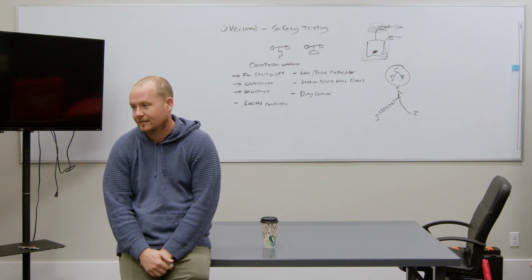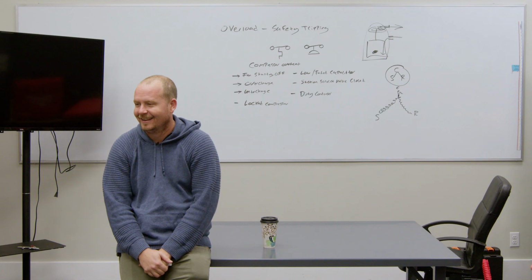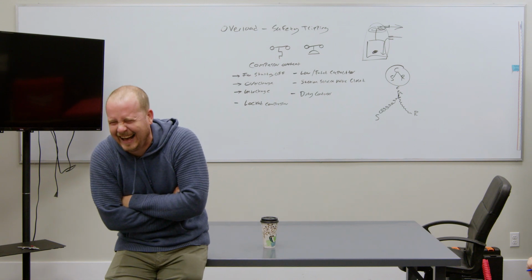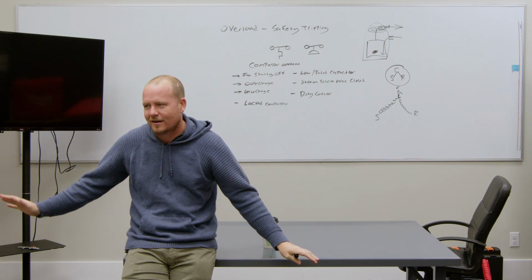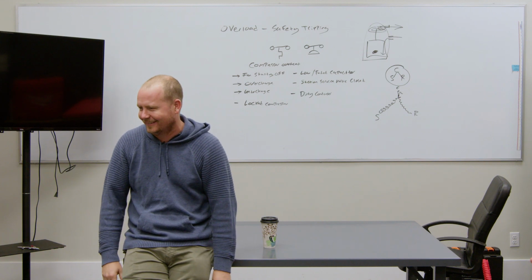It's possible. A lot of people get distracted by the ice and they don't check the compressor, but I always ohm it out every time, and you'll find that it's overheated a lot when there's ice on the coil. That's good. It may have seemed like it was running just fine, but I went out and I ohmed it, and the thing had an open thermal overload.